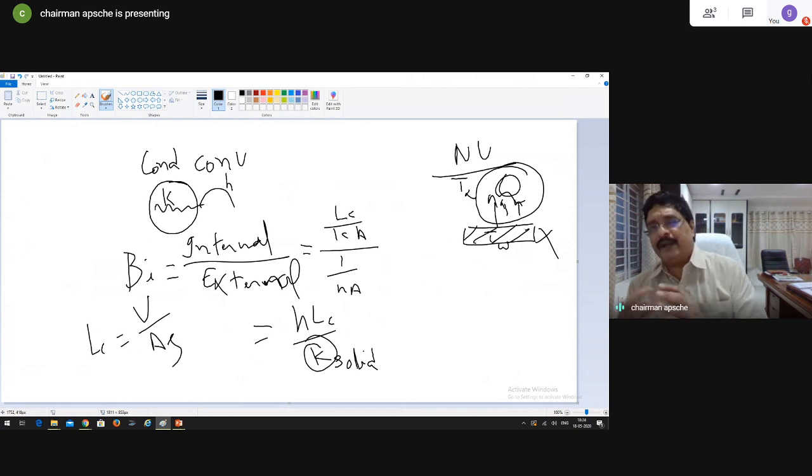And take, for example, a liquid metal, like flowing lead or something. The viscosity is very, very high. The molecular density is very, very high. Intermolecular attraction is also very high. The molecules cannot move very freely. In such a case, convection resistance is very, very high, whereas the conductivity of the liquid metal is very high, and therefore conduction resistance is less.